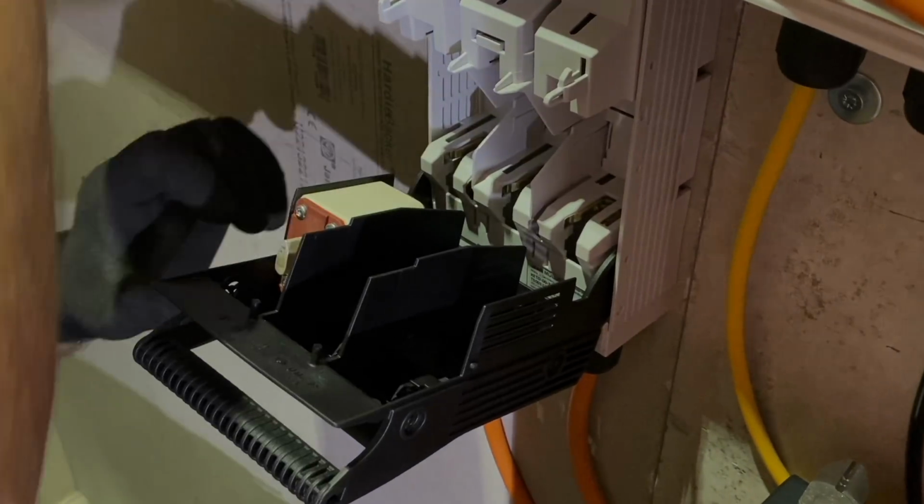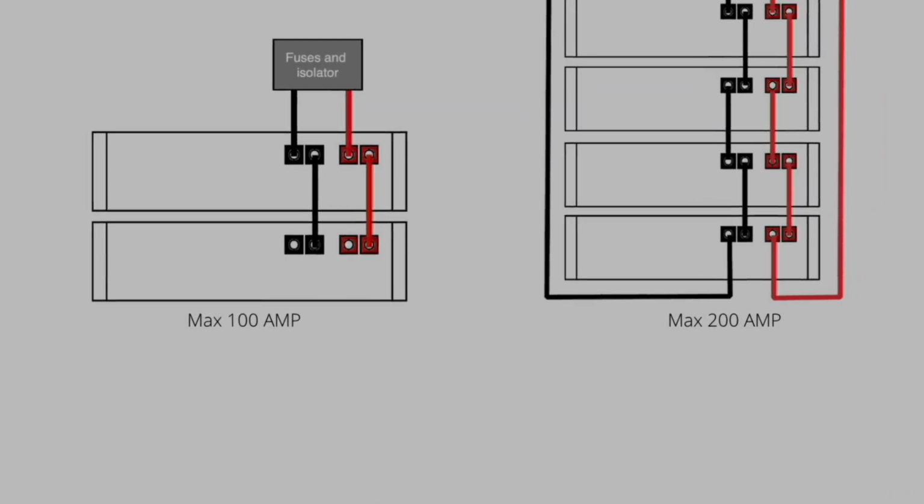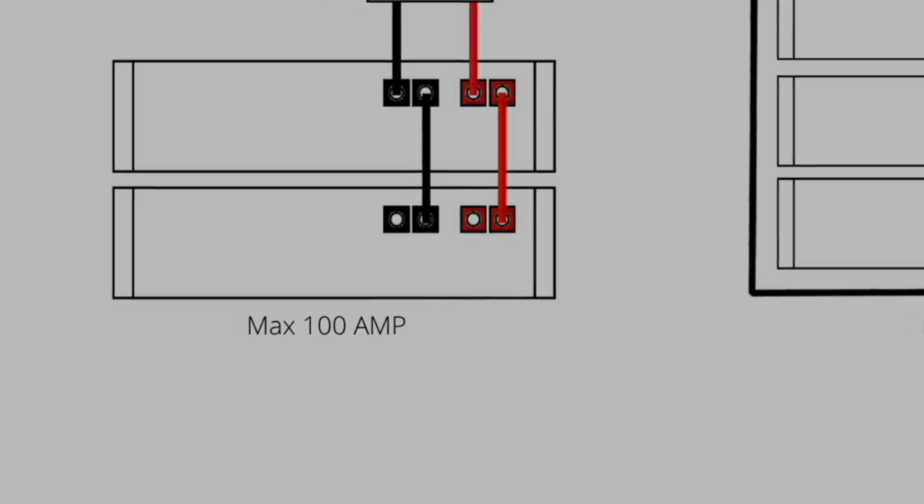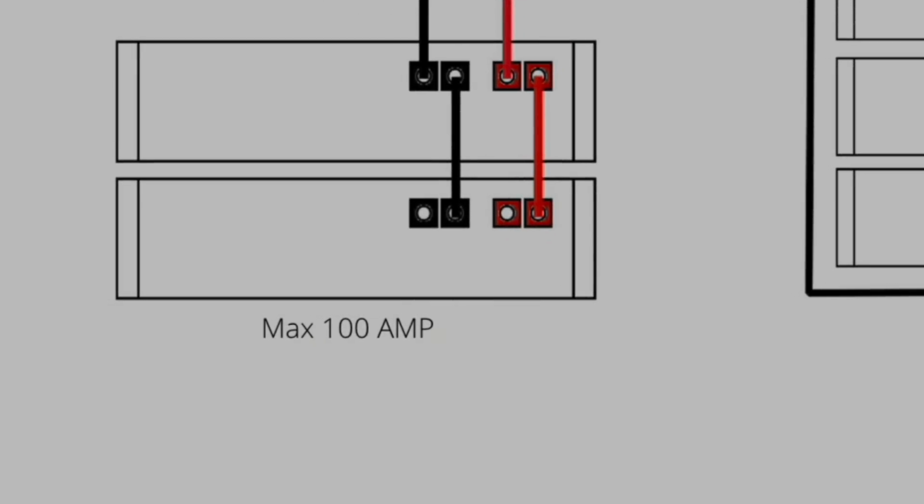Our battery has a short circuit capacity of 350 amps, and this can be found in the manufacturer's guidance, as are the fuse sizes, which it states need to be 100 amps. So we have seen how we can protect the installation and the cables within it. But what about those additional protection requirements?